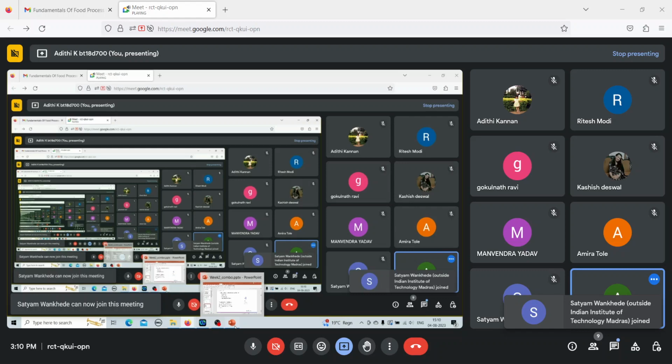So in this case, your strains will be equal to each other. That is, total strain is equal to strain in the spring, equal to strain in the dashpot. This is for a Kelvin model. Whereas the stresses will be the summation of the individual stresses. So tau is equal to tau spring plus tau dashpot. This is for the Kelvin model.